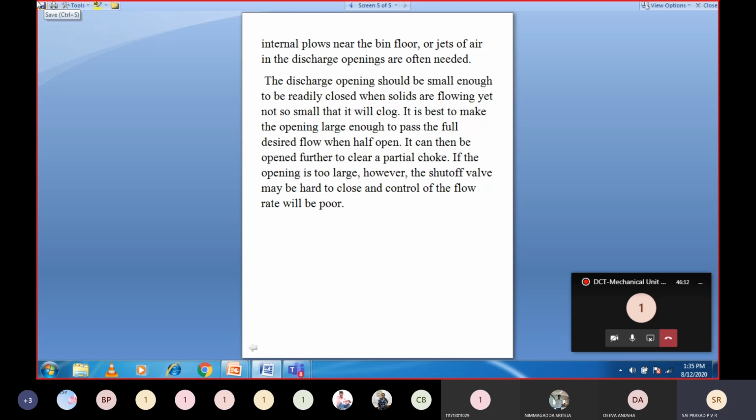For example, take the case of a municipal water treatment method. The first step is measuring the hardness of the water. After measuring the hardness, accordingly we will be measuring the quantities of alum, soda ash and activated carbon to be added. That is measured, and then what will happen? We will be opening the valves because you know the quantity and you know the flow rate. Hence we will be fixing how much amount has to be discharged onto the conveyor belt.